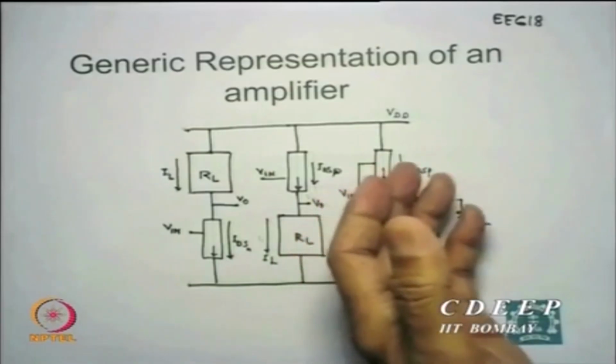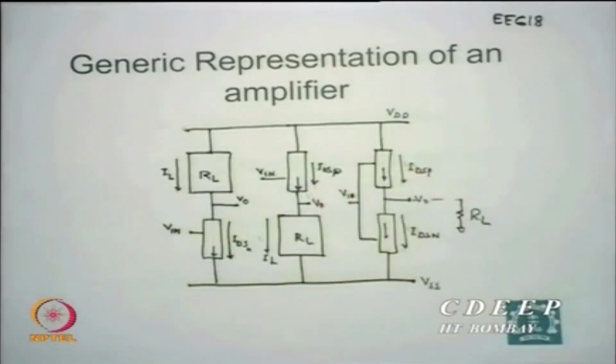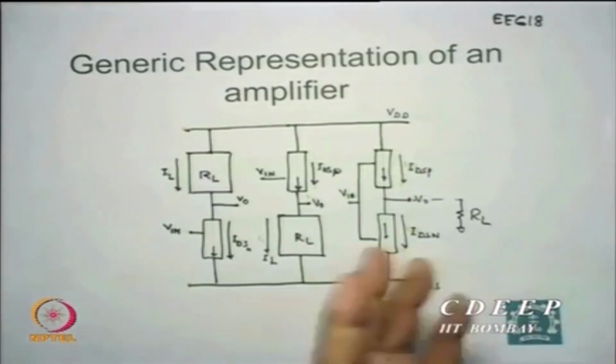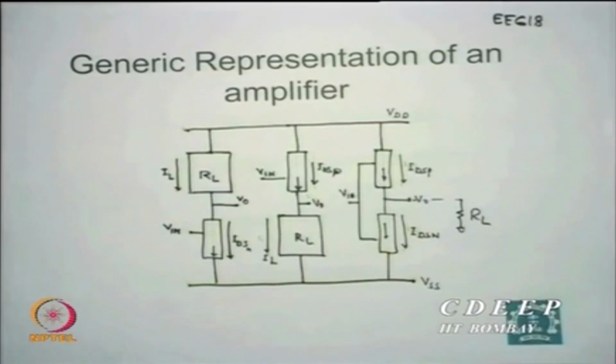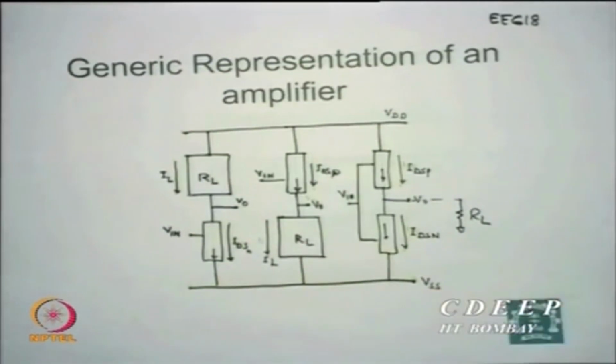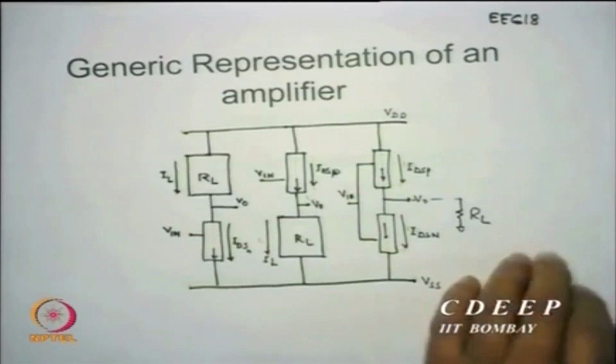Whatever is the output resistance of this is useful for the next stage connections. Okay. So the next stage input resistance is the output resistance of the last stage, and that we call R0. Okay. So in an integrated circuit, not that RL will never be used, but in general connections are not through a load, actually the output resistance itself is acting like a load.